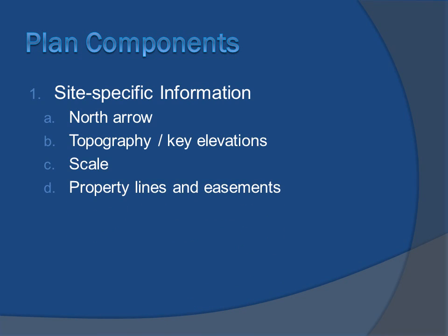And back to scale, what are the 4 major scales we draw in, or we read plans in landscaping? 1/8, 1/4, 1/2. Is it 1/16? There's 2 architect and 2 engineer scales that we'll see a lot, and you should know them. The first 2 you said were right. 10 and 20. 10 scale and 20 scale on the engineer, and then 1/4 and 1/8 on the architect scale.